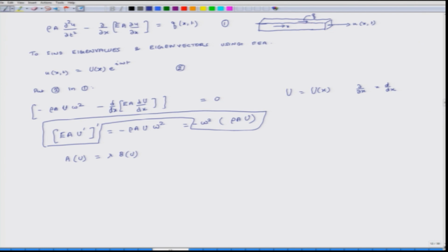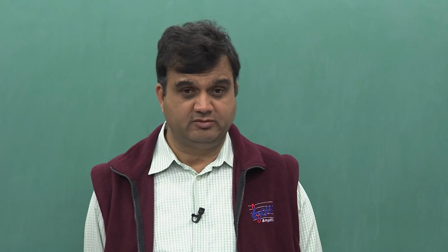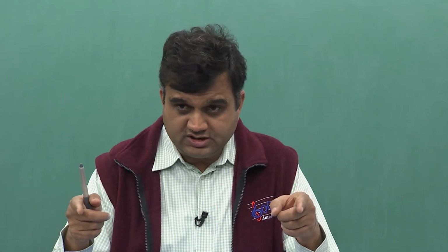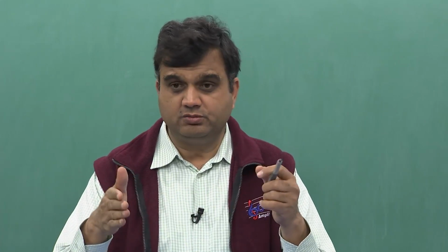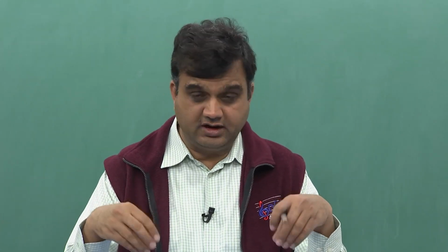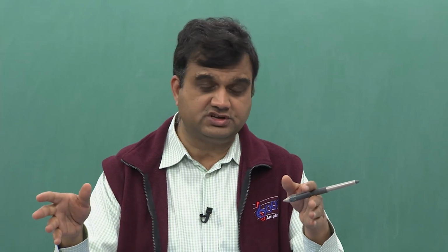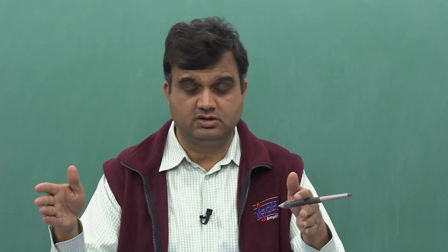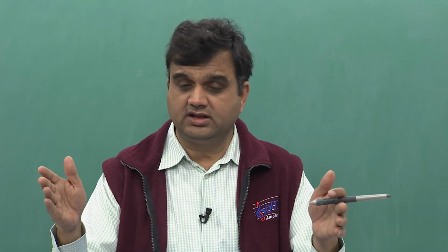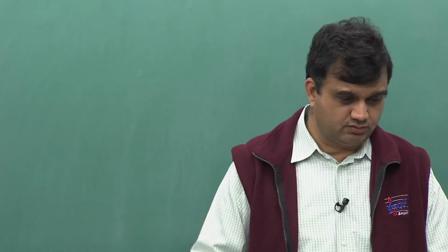Okay. Now, at this stage, I am going to solve these equations using the finite element method, and all of you already know how to solve this problem using the finite element method. The first step is we will break the domain into small elements. The second step will be, we will assume an interpolation function for u. We will plug those things here. We will find the residue of the overall thing over the entire element, multiply it by a weight function, equate that weighted residue to 0, weaken the differential form, and develop a system of equations, and then we will solve those equations to get our answer. So, that is the overall process, and that is what we are going to do.